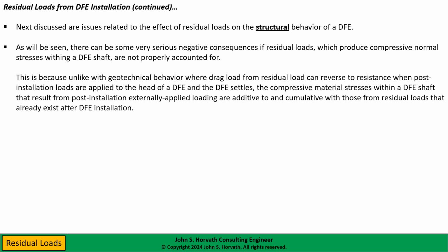So again, with the geotechnical aspects, if we settle the DFE enough, we can cancel out the drag load and convert it to resistance. But unfortunately, we can't do that with the structural aspects. That's because all the loads involved are compressive in nature. They're compressive loads, compressive stresses, and they simply will build up on each other.